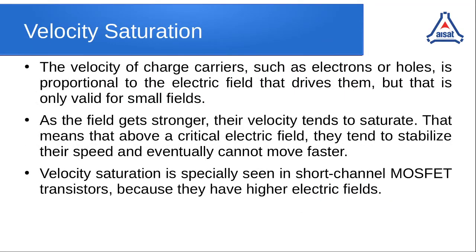The next effect due to the short channel is the velocity saturation. The charge carriers move with a particular speed, which is the velocity of charge carriers. As you all know, the charge carriers could be electrons or holes. And this velocity is proportional to the applied electric field. That also you know. But this dependency on electric field alone is valid only for small fields.